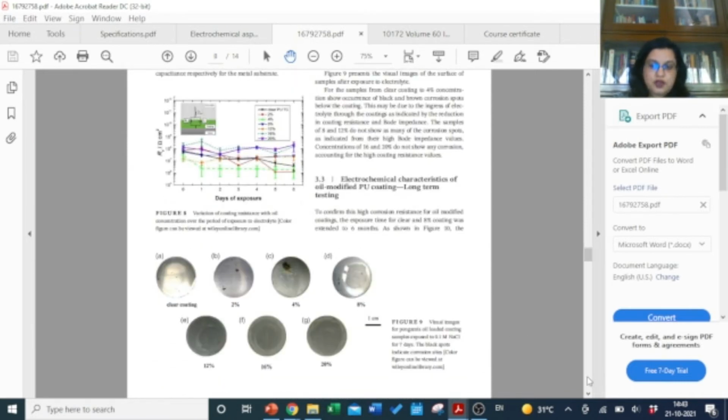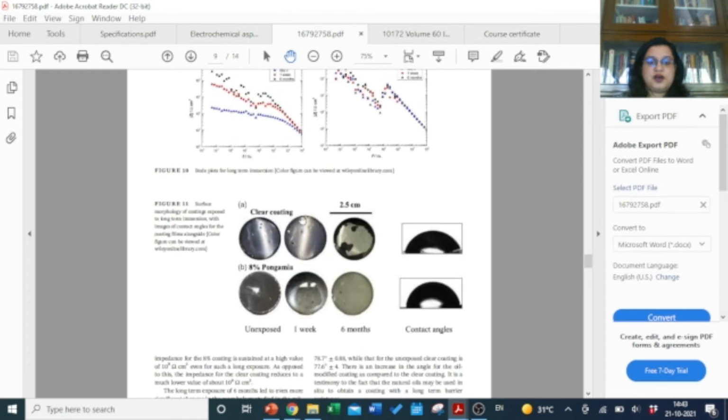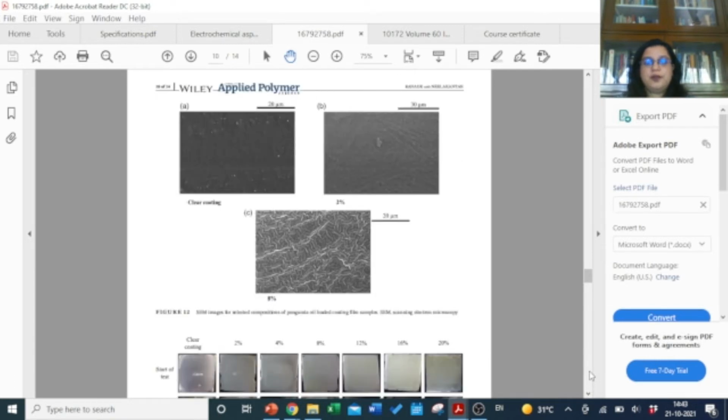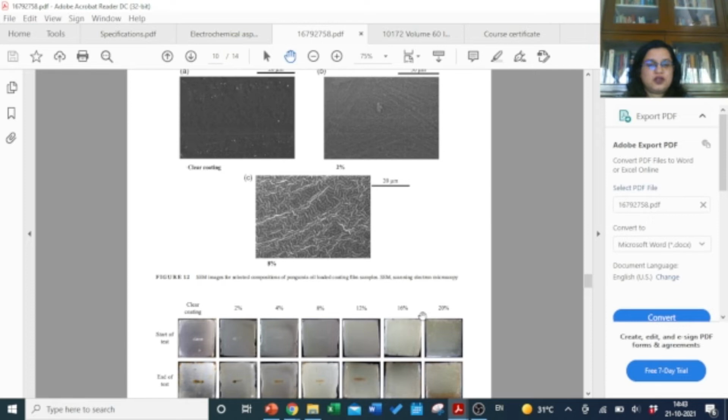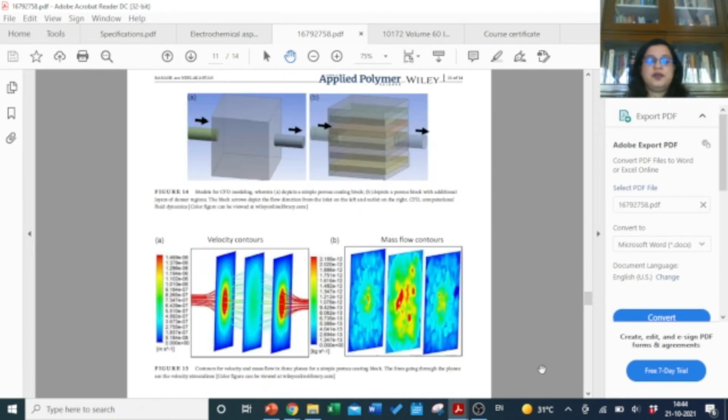After that, of course, we go on to the qualitative measurements, and as you can see here, after 6 months you do long-term measurements and redo these impedance tests, so that we can relate these good, excellent, very good ratings to the quantitative value, and that is helpful in a better way. Further, the salt spray test also gives us which one is the better coating. But as you can see, there is no way to quantify, because this looks good and this also looks good. At face value, these look quite similar, so we really don't know which one is the best. That's why electrochemical impedance can help in quantifying.